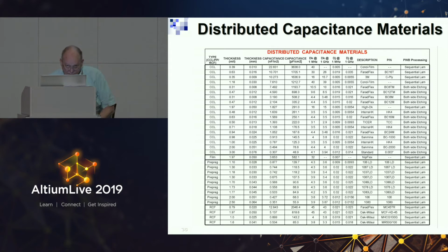And so I give the nanofarads per square inch and the picofarads per square centimeter of these materials. So all of these are suitable to provide distributed capacitance for high frequency noise. There's not just 7, there are 37 out there.